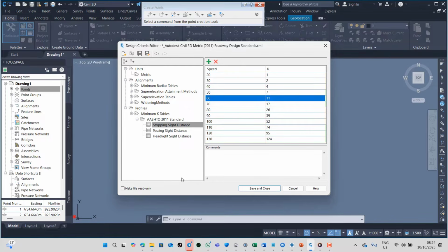Now at a particular speed, and our speed is 60 km/h, if there is another car approaching from the other side, or maybe a cow or sheep crossing that particular road, by the time you apply your brake there is a particular distance you are supposed to have to be able to stop, which is called the stopping sight distance, in order for you not to hit that car which is approaching or whatever is crossing the road.